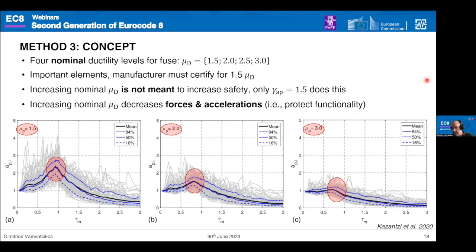And this trend continues, but you'll notice that we've put a maximum ductility of 3 that you can employ, because after a while, what it means to have a ductility of 5 in a component, you may get it, you may not, it's just pushing it too much.